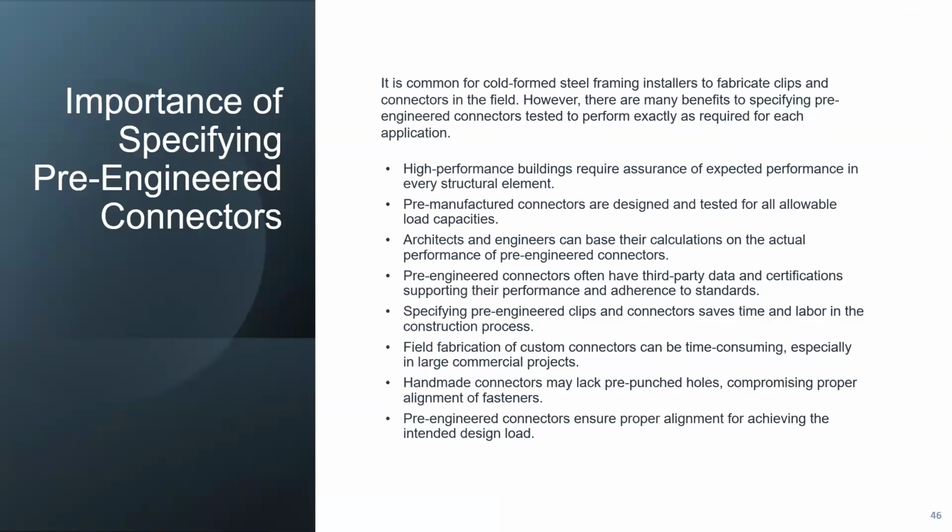Now, it's very common for cold-formed steel framing installers to fabricate clips and connectors in the field. Like I said, it's been more recent that connectors are actually designed rather than just fabricated. And I think that's because they've seen many benefits to specifying the pre-engineered connectors, and because they are tested to perform exactly as required for each application.